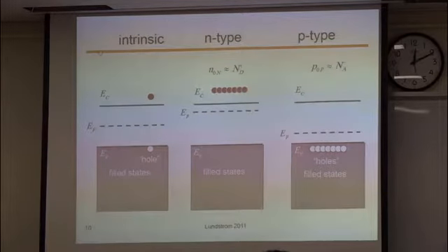In other words, the number of holes increases. A hole is the opposite concept of the electron. Electron is a sort of negative charge, but hole is a sort of positive charge. So by inserting boron, we will have more holes and fewer electrons. One boron insertion will generate one hole, and two boron insertions will generate two holes, in this way.